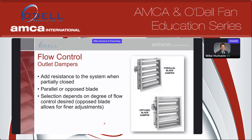So we're going to look at outlet dampers first. An outlet damper, basically, is mounted on the outlet of the fan. All you're doing is, as you're closing the blades from open to 90 degrees to closed, you're adding resistance to the system. And as you add resistance, you're going to change where that fan actually operates. The couple options you have are a parallel or opposed blade. And a couple differences there.